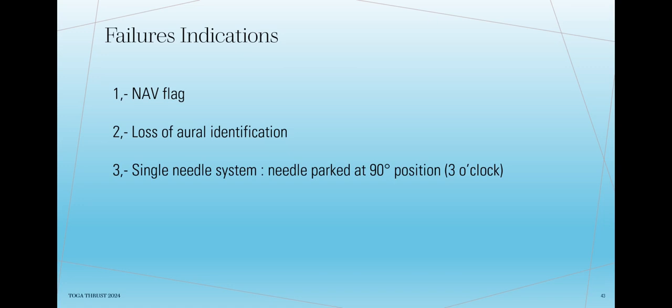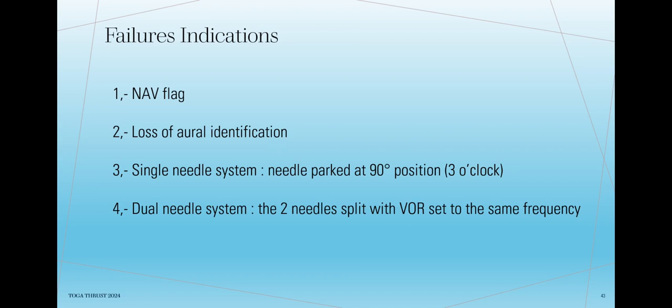Failure indications. NAV flag. Loss of aural identification. Single needle system, needle parked at 90 degrees position, 3 o'clock. Dual needle system, with VOR set to the same frequency.